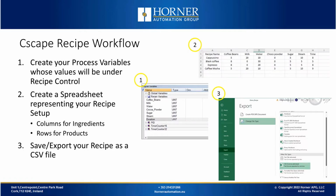Now let's go through the workflow for adding recipe functionality to your application. Typically, you're going to add recipes toward the end of your application development cycle when you've got everything set up the way you want. First, you need to make sure that any process variables that are impacted or modified by recipes have already been created. Next, I like to start with a spreadsheet to set up my recipes. I typically use Excel or some other spreadsheet program for this. In the columns, I'll add my ingredients, and in the rows, I'll add my products. Once I've done that, I export that as a CSV file. So I'm ready for Cscape to import that information.